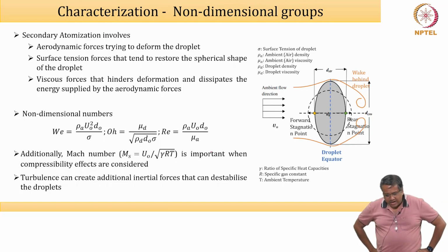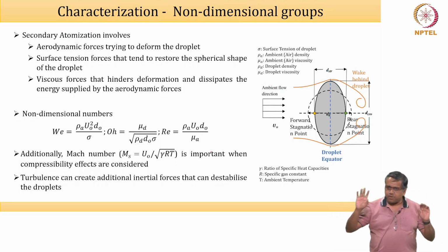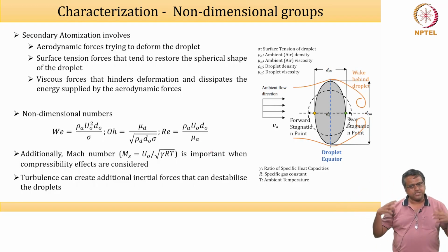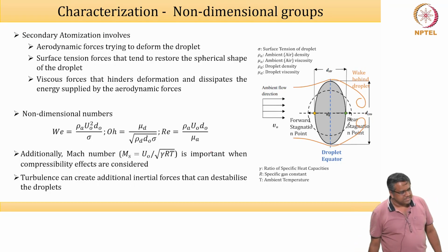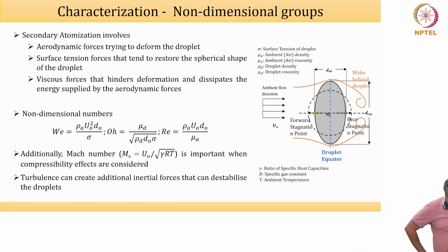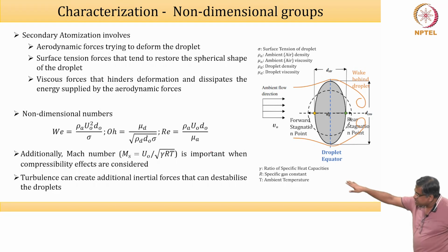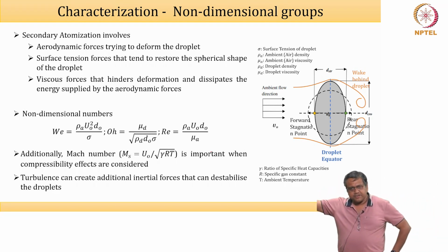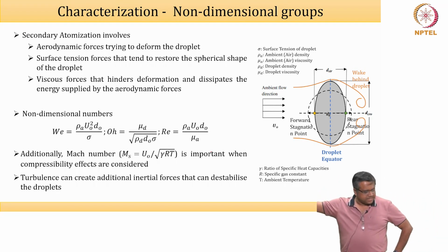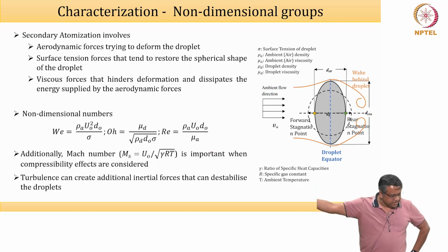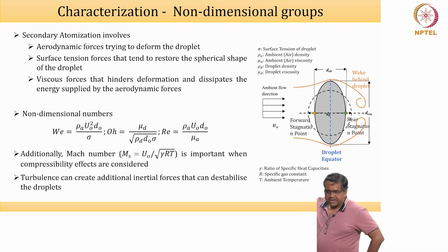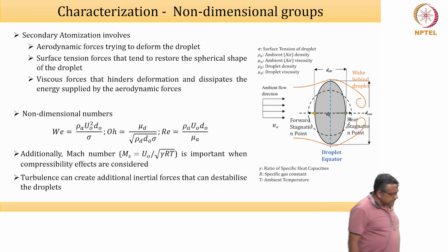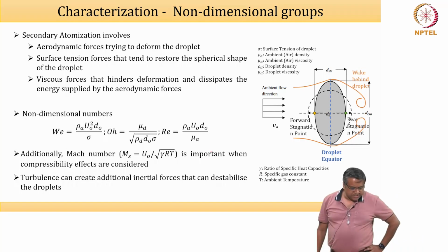So, a quick word: I have provided evidence of what happens. The vibrational mode of breakup is something that you can even do at your home. I think that is not a useful example to show. The non-dimensional groups, we have mentioned 3. These are already well characterized: Ohnesorge number, a little late acting, a little laid back essentially, then Weber number and Reynolds number. There are actually not 3, you can combine them into 2, okay? But there are 2 other dimensionless numbers.